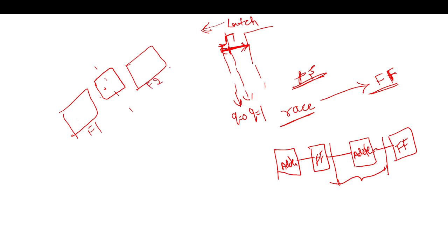Have you heard about scan chains? Okay, so if I want to test this circuit, the pins of this adder or any other block won't be available externally. If I can apply any input to this flip-flop and also see any output, I can test this adder block.